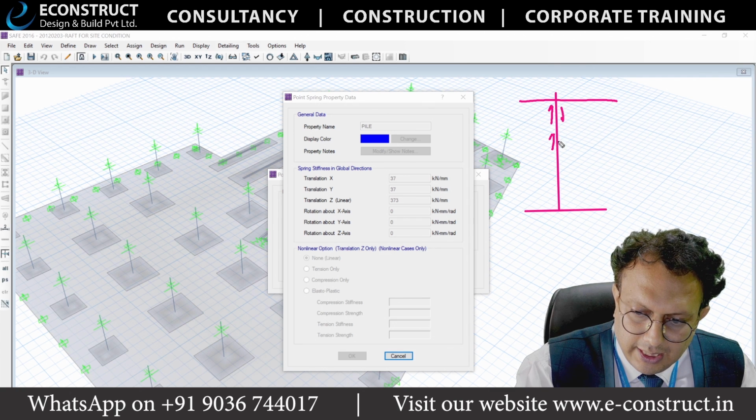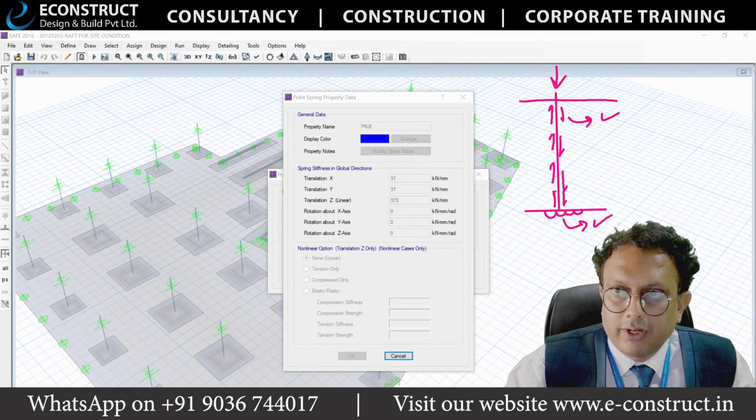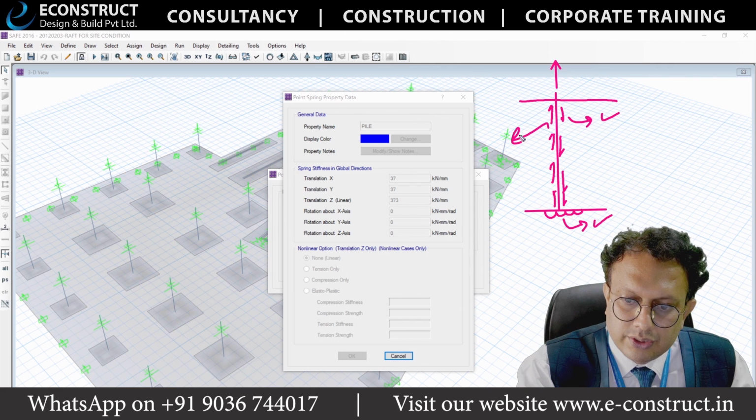Skin friction is there everywhere, and here you are having the end bearing. So whenever there is compression, this will help. This also will help. But if, for example, this is in tension, this will help, this will not help.